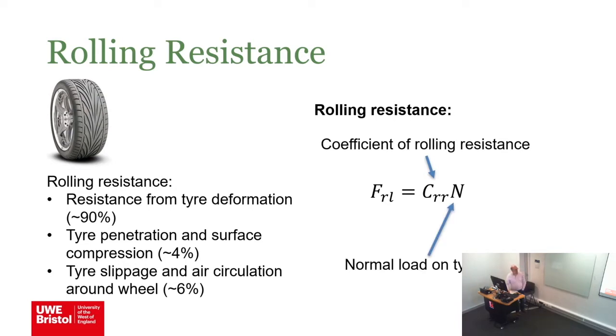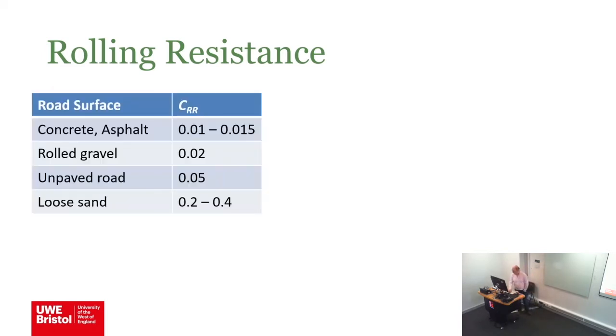Now clearly, rolling resistance only impacts the car when it's moving. If you're trying to model a vehicle with rolling resistance, you need to make sure that it's only applied when the car is actually starting to move. For aerodynamic drag, there's a V term in that equation, so when V is 0, drag is 0, so that works. And some example CR values.